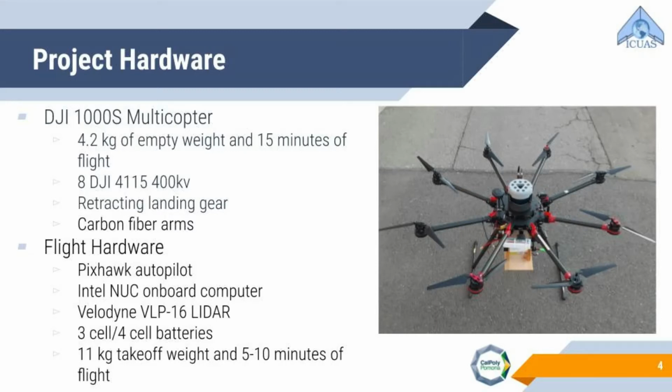It offers a large carry capacity for onboard processing and resilient LiDAR mount protection. The flight controller we used was a PixHawk2, which took commands from the onboard computer, an Intel NUC Plus. It processed all information coming from the most important piece, our LiDAR, the VLP-16. With this added weight, our flight time was reduced from 15 minutes to around 10, but it was still plenty of time to complete our mission.